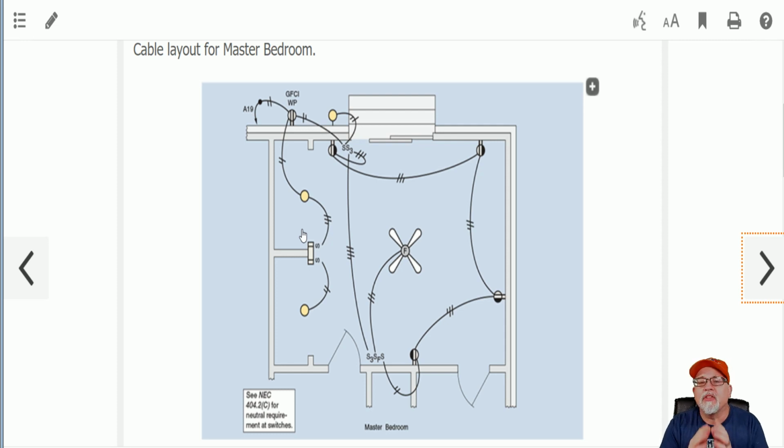And I can tell you, there is one nightmare scenario that runs through every electrician's mind when it comes to residential wiring. Did I feed every circuit? Did I leave anything dead? In other words, I forgot to loop in something, so that once it's gypsum board up and everything's finished, all of a sudden I have a circuit that's not working because I forgot to run a home run or I forgot to loop something together. It's a nightmare that electricians never want to experience. So it's important to really lay out your circuits and double check them before you say that you're done, making sure everything works.